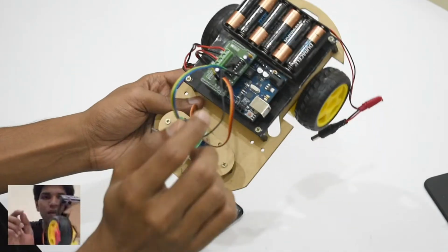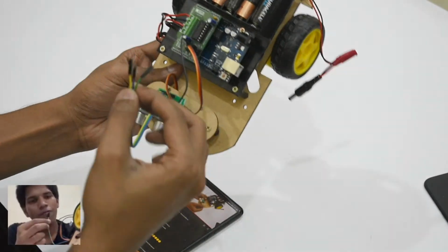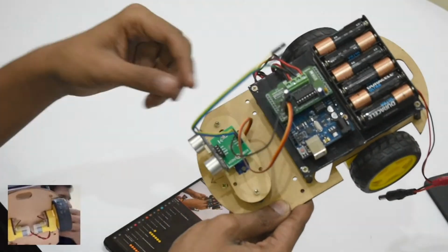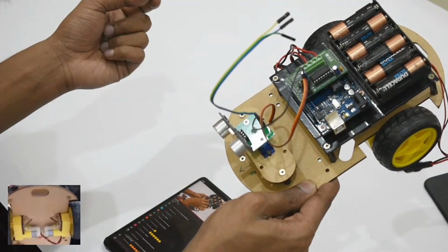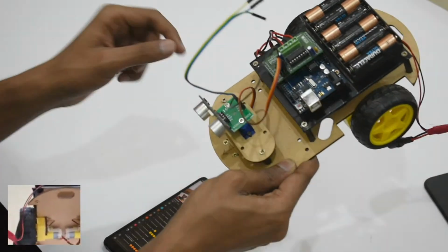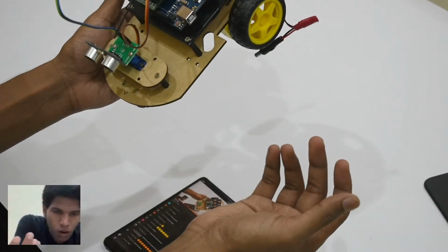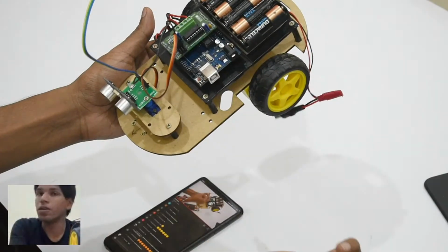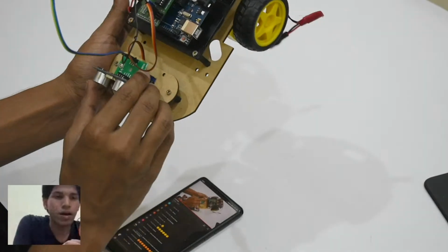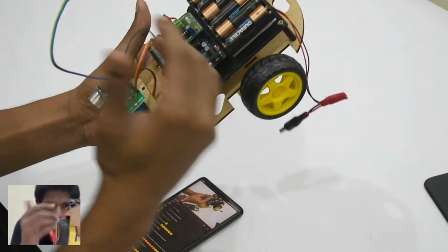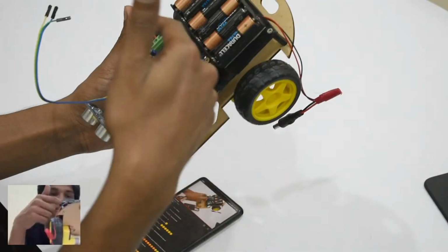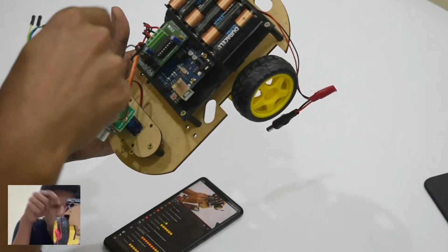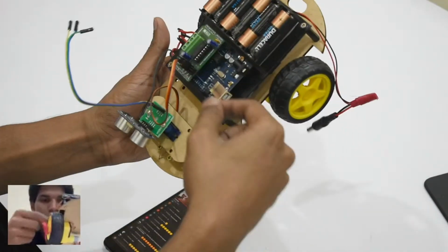Okay, once I have done that, other than that, you have 2 more wires coming for your echo and trigger pin of your ultrasonic sensor. Who will know which pins we have attached the wires to? See, all the pins are labeled. Whenever you get these circuits, when you read those circuits, you will be able to see which pin has what part, which pin is what activity.